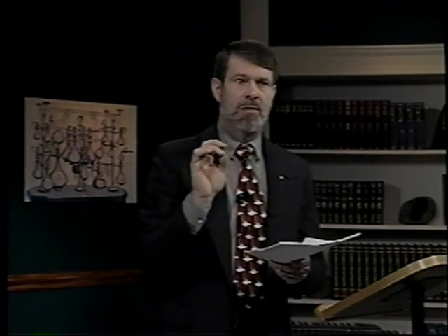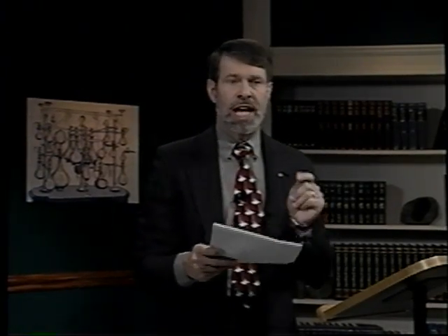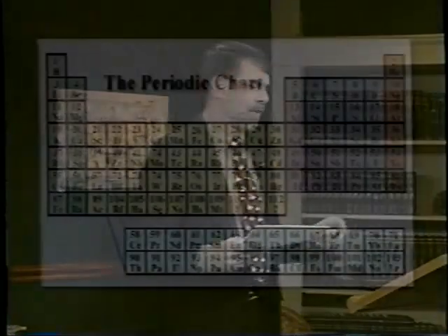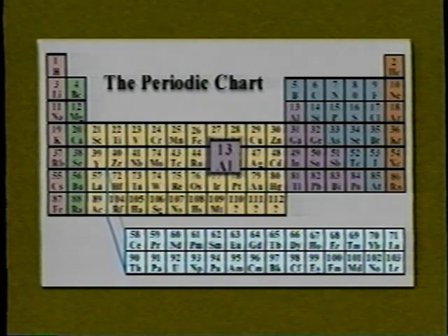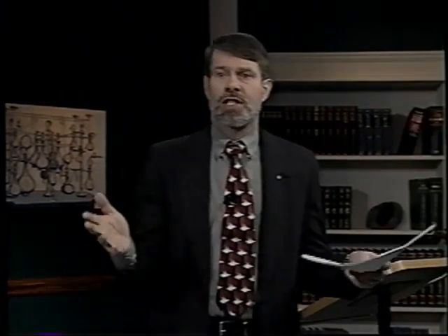Now, apply the same logic to a silicon crystal in which a single atom of aluminum, element 13, substitutes for a silicon atom. In the periodic table, aluminum is right next door to silicon. Well, here with 13 electrons, including 3 electrons in the outer shell, you have one too few electrons. There's essentially a missing electron in this silicon crystal now. A missing electron is called a hole in the terminology of electronics. And a hole is essentially the absence of an electron. It carries a positive charge.